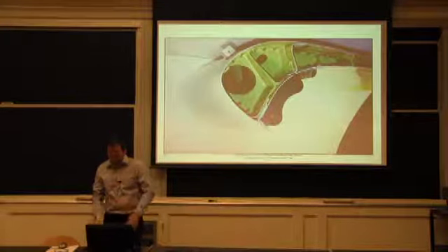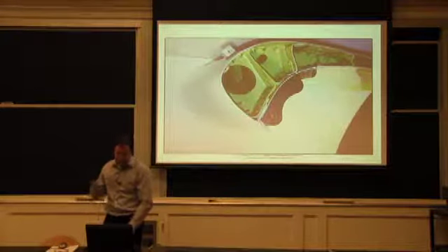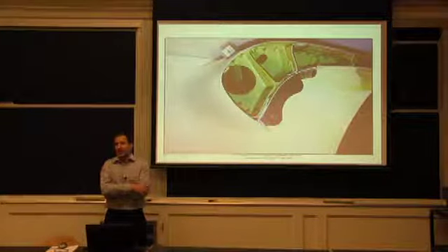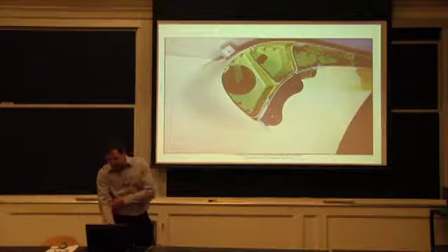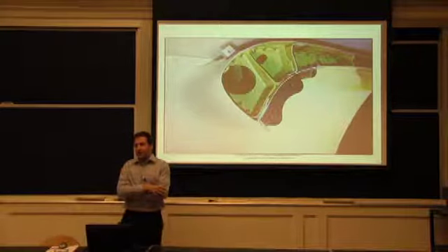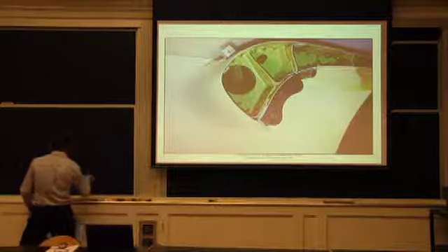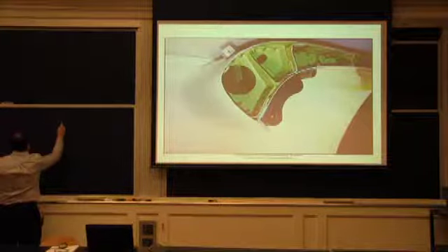So they went on and picked that titanium component as a wrought plate, 3.5 inch thick, a slab essentially, and that's what they were using to machine out this detailed rib structure that had only about 1/8 of an inch of thickness in the center. So if we look at it in a cross section, this is pretty much an I shape. So you have the top surface, you have the web here in the middle, and the web at some location even had a hole in it.